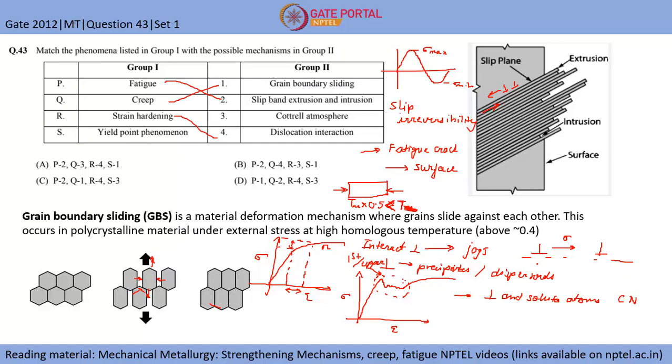Now, as soon as this stress is reached, the dislocation is free to move and it is not pinned by the carbon and nitrogen atmosphere. Hence, the stress drops again here. This is called the lower yield point. Still there will be some serrations here because the carbon and nitrogen are not completely detached from the dislocation. Hence it will move like this, and at this point the moving dislocations are completely away from this carbon nitrogen atmosphere.